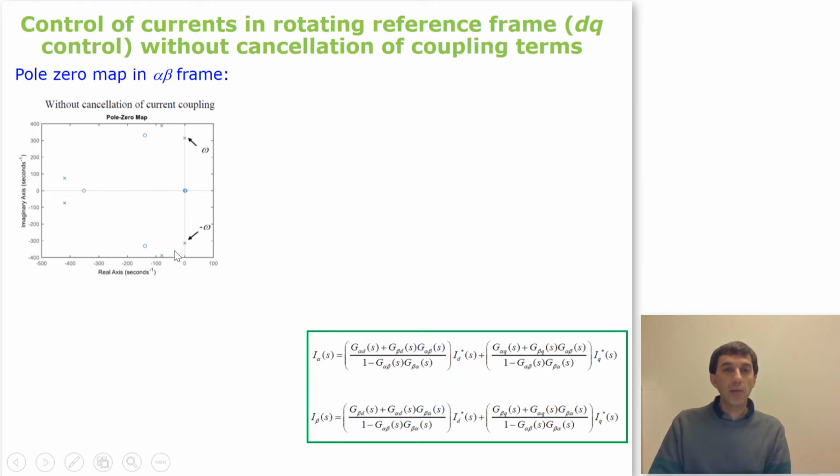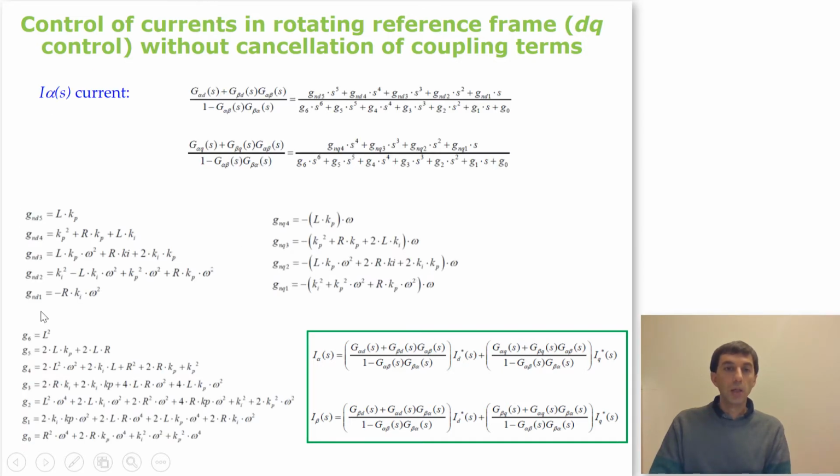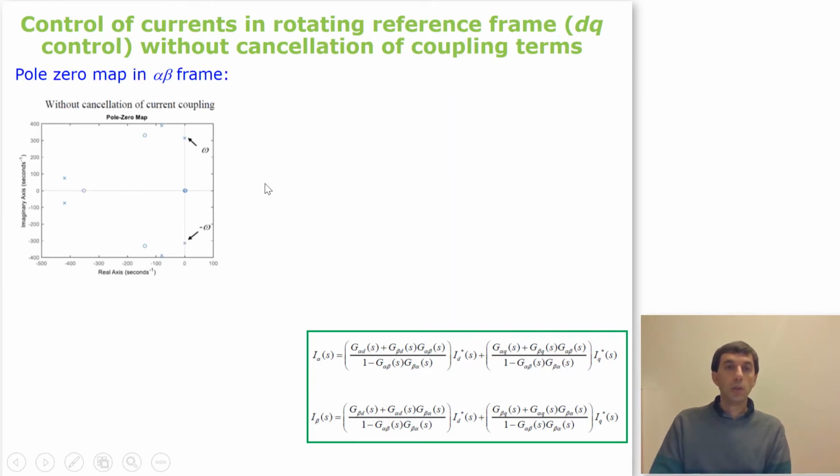And now we have another 4 poles. Just remember that here we have 6 poles at the denominator, 2 here at steady state, and another 4 with real part for the transient response or the natural response.